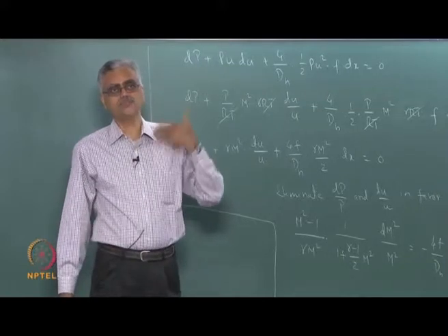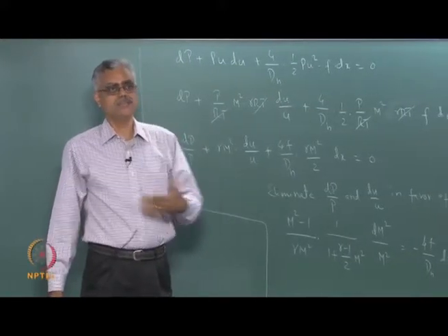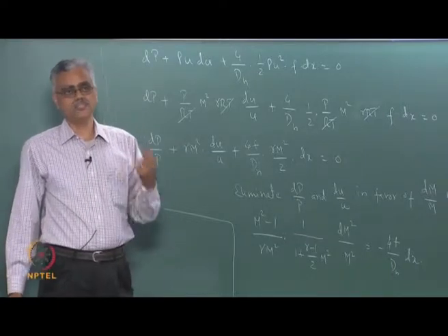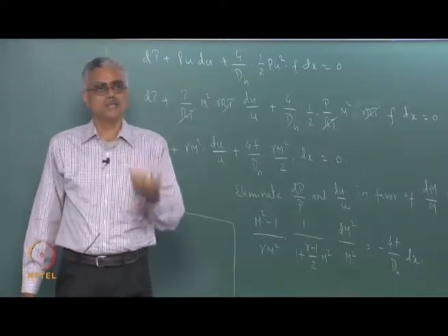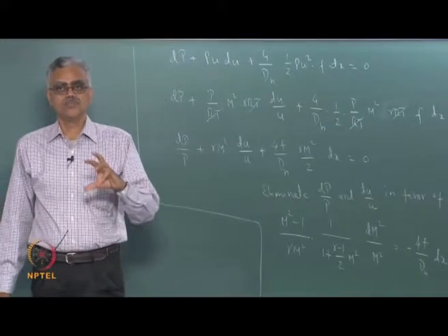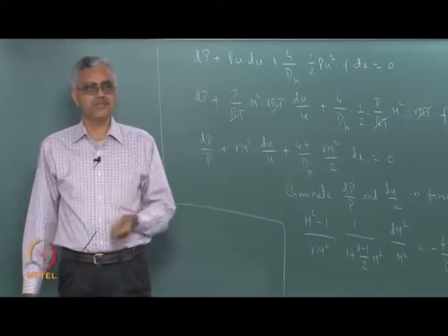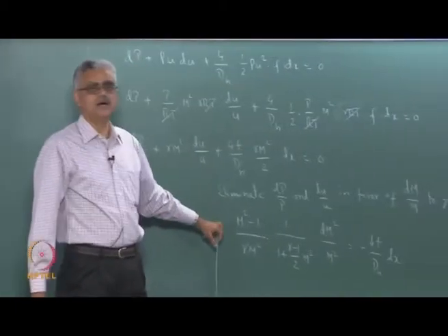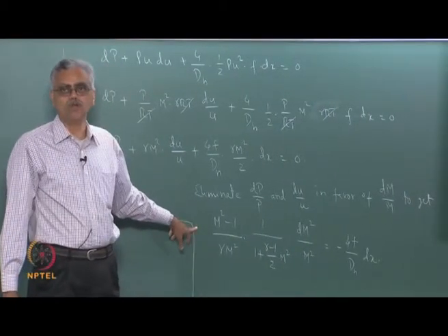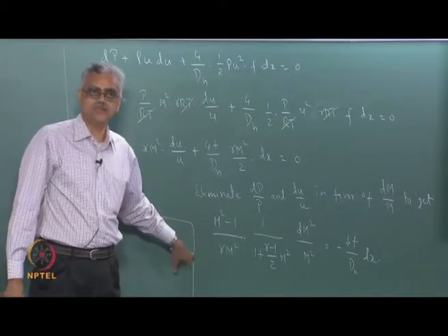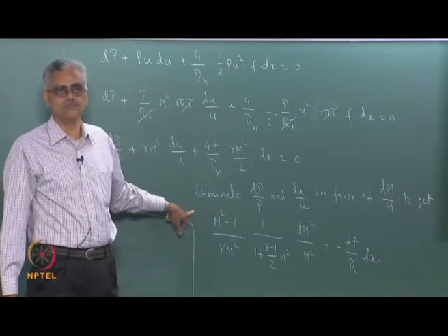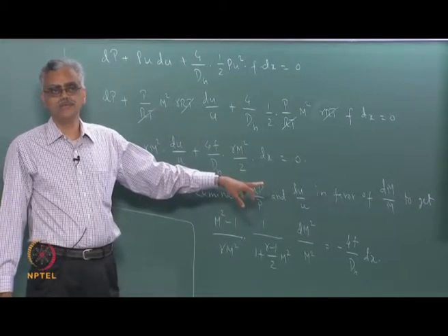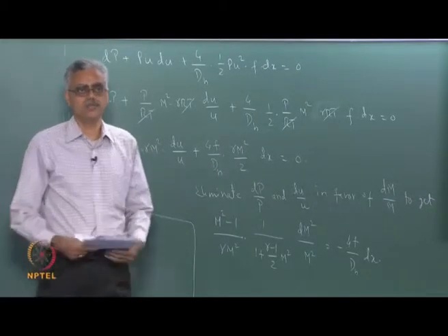Now this means I have to solve a nonlinear equation every time, and so I need to have very complex tables. The other problem is such nonlinear equations also have multiple solutions. So we avoid this by using the same trick that we used before. So what I am going to do is take a certain value of M1 and integrate from that M1 to M equal to 1. So the right hand side, if I do that, will give me L star corresponding to that Mach number, right.